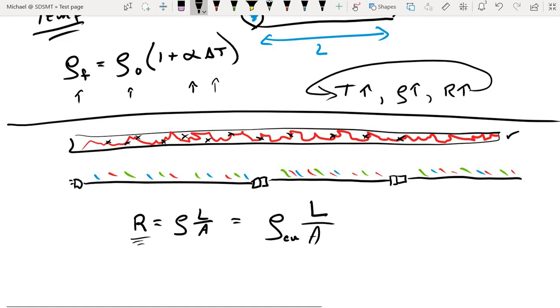Either the wire itself could melt, or, as is more likely the case, before the wire melts, the protective plastic sheathing on the wire will melt, possibly catching fire, or at the very least it could spark or arc and then catch something else on fire as a result.